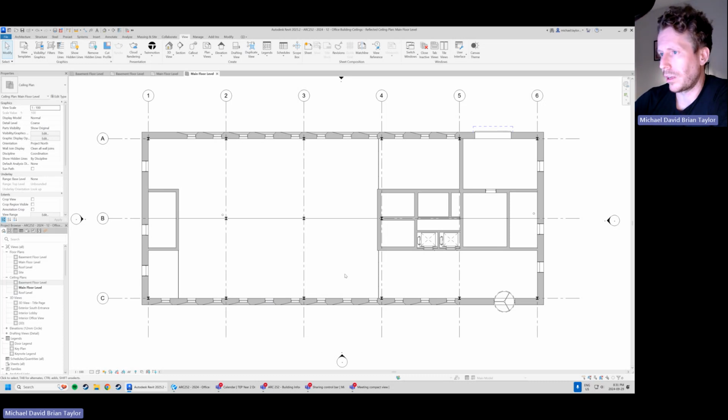So how are we controlling what we see on this specific view in this specific case? Really important. All of the geometry, everything that is in the BIM model, inside of the Revit model, still exists. We haven't deleted anything. We haven't messed with anything. We've just taken a look at turning on or off the objects within this particular view. Geometry still exists.